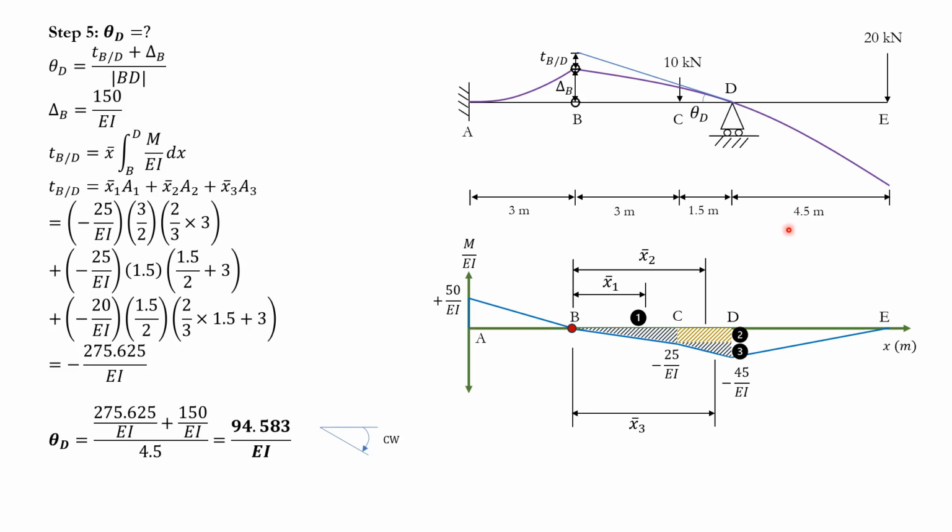That's clockwise. Simple as that. So many ways to determine that. But the rule that I mentioned about the first theorem does not apply here, because we're finding the rotation using the second theorem. Just keep it in mind. Seems like a lot of details, but if you just do the problem a couple of times, it's just going to become muscle memory, I'd say.